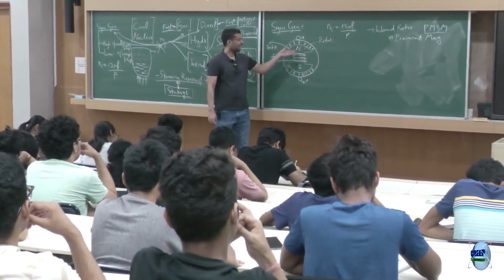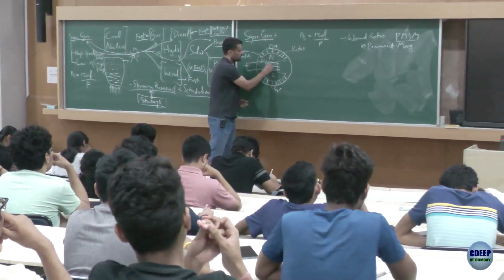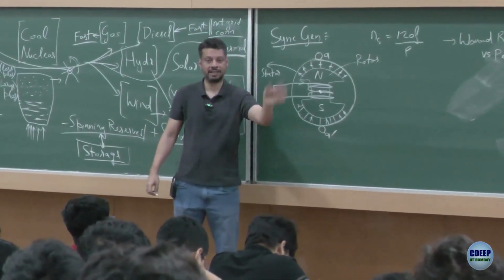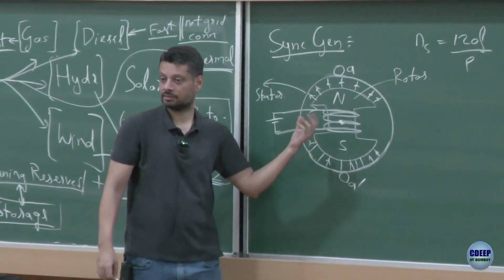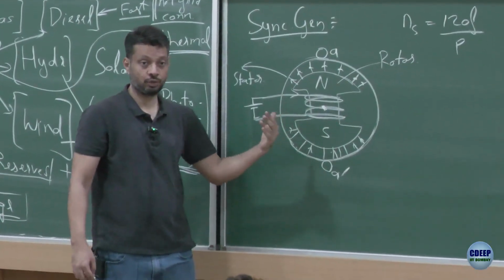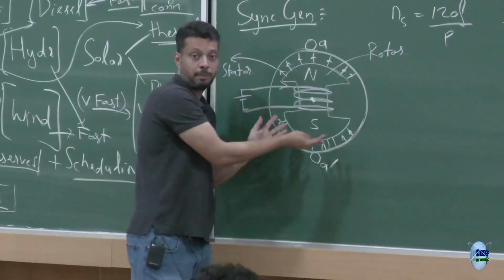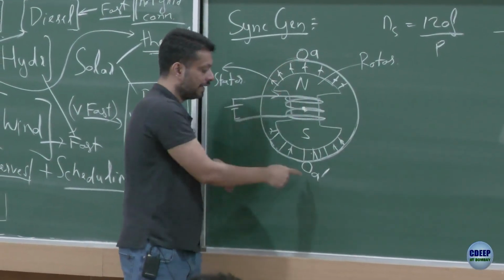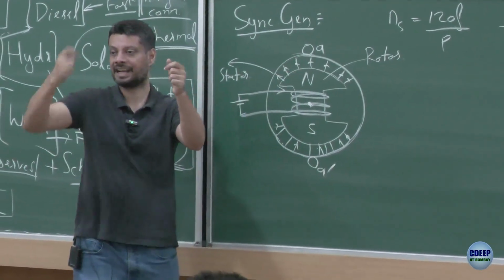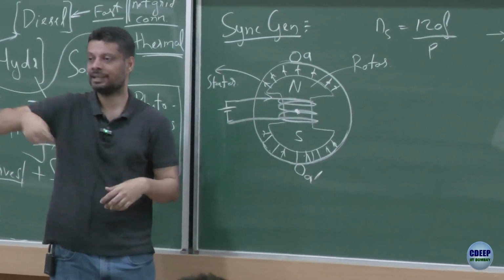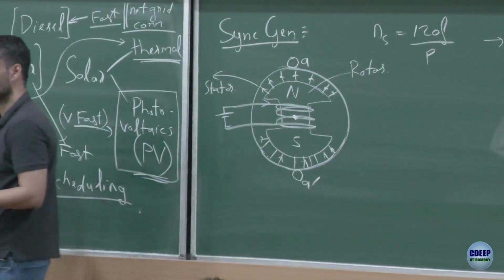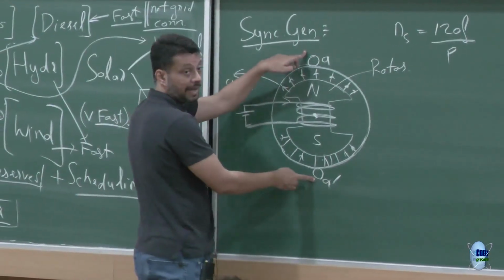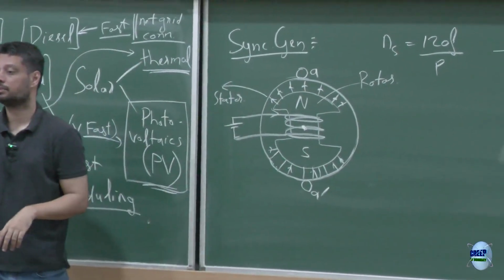Okay. Now imagine I connect this to a shaft and put a turbine there, and the turbine is rotating, so this shaft is rotating, right? And if this shaft is rotating, this whole flux pattern is rotating. I have a coil here which I have kept open loop, but there are N turns, so this N-turn coil would have a voltage induced in it. This stator coil AA prime will have a voltage induced into it.